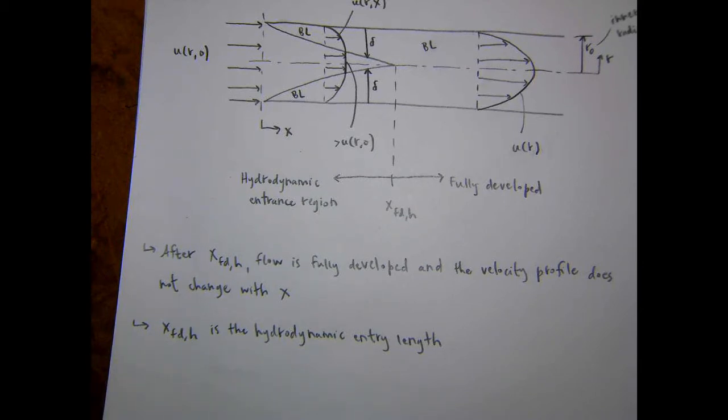So in internal flow, in addition to having laminar or turbulent flow, which affects those things, you also have to determine whether or not you're in the entry region of the pipe, or the fully developed region. So there's like 4 different things to keep track of when you're considering internal flow. So next time we will talk about some expressions for how to determine which region you're in, and then how to calculate the Nusselt number and the friction coefficient. Thanks.